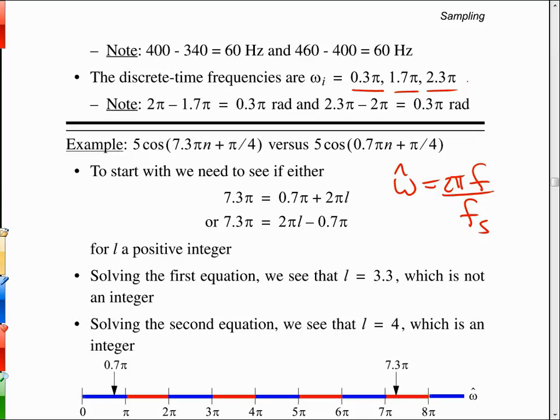And the principal alias is right here, and why is that the principal alias in the digital frequency axis? Remember last time we spent a lot of time on the principal alias band in the analog frequency axis, and that was 0 to Fs over 2, remember? So what's the equivalent band on the digital frequency axis for being a principal alias from last time? Between 0 and pi? Yep, exactly. Because all you'd have to do is plug in place of F here, Fs over 2, and that's the maximum frequency we can go up to. We can approach that value and not have aliasing, and we plug that in, we get the Fs canceling, and we get 2 pi over 2, which is then pi. So that's the highest frequency we can go up to before aliasing commences.